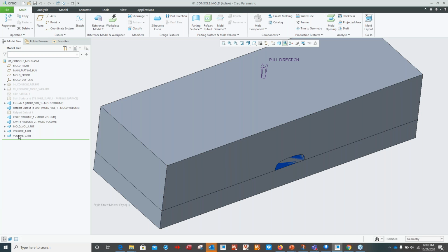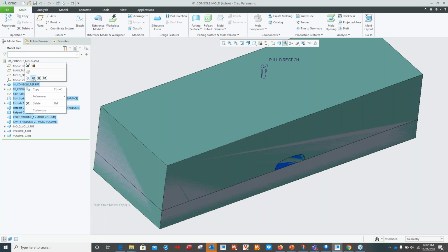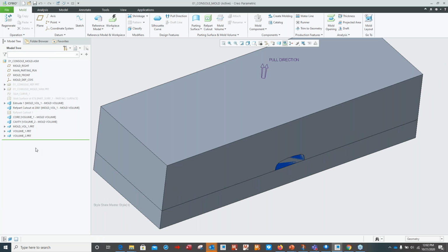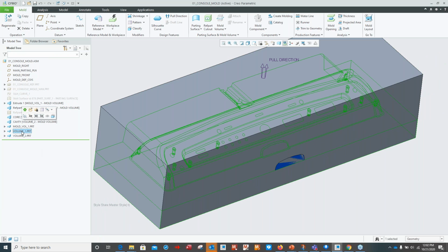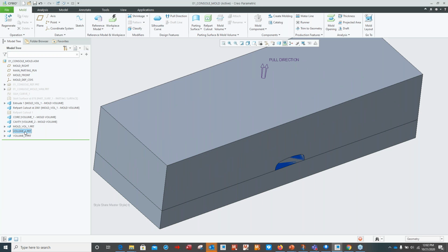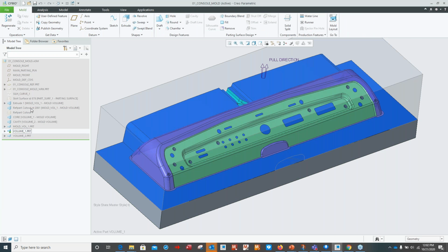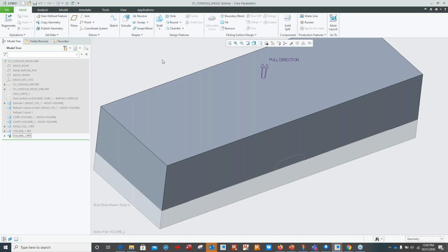We select OK. As we can see now, it generates the part files required for this. So we're going to turn these other unnecessary geometry off. So this should be named, we can rename this. Okay. Well, I skipped the naming, but we can rename that and assign that. So we've got this volume for the core side. Actually, and I want to activate the cavity side.